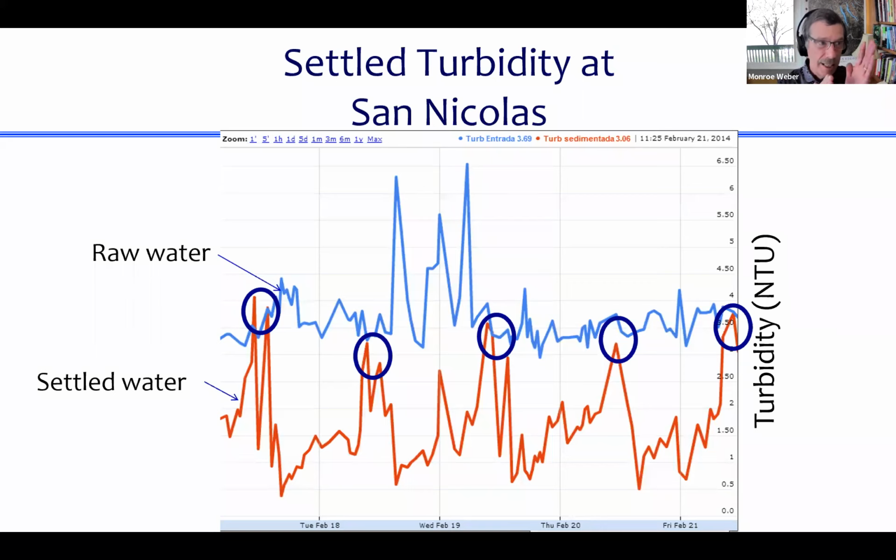Because in the flocculator, that means the fluid deforms more easily, and so there should be more collisions. And in the sedimentation tank, the terminal velocity of the flocs will be higher because it's less viscous, and so we should be able to remove them easier. So viscosity was a dud as far as explaining this.